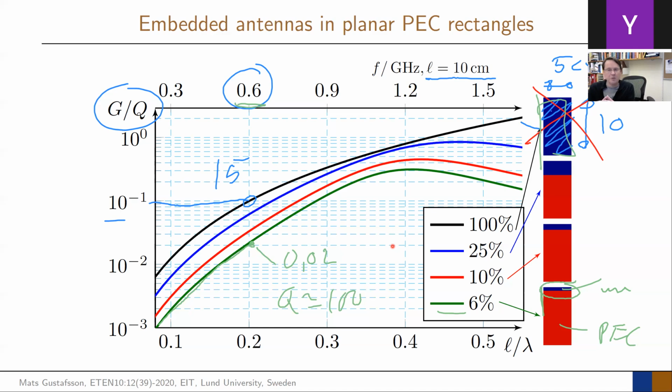The only thing you can do to go around it is to break the relationship between this Q factor and bandwidth. And there's a lot of work nowadays in that direction. And that is really, in some ways, using what's called adaptive matching. So when you start changing the frequency band and the way you hold the phone, you can adaptively rebuild your structure. And that can give you a bandwidth that you would like to have. You can let it change in some ways. And that can then increase the bandwidth for a given Q, but there will still be a lot of these reactive fields pumping forward or back around your structure.